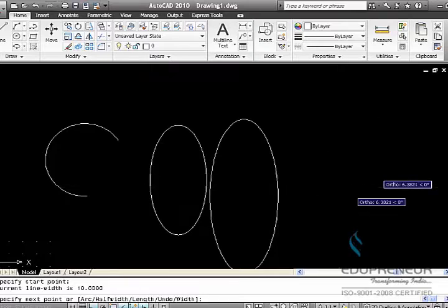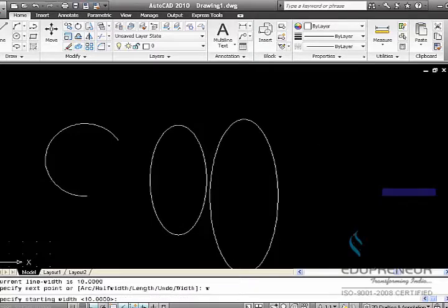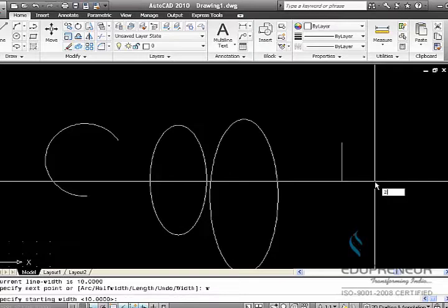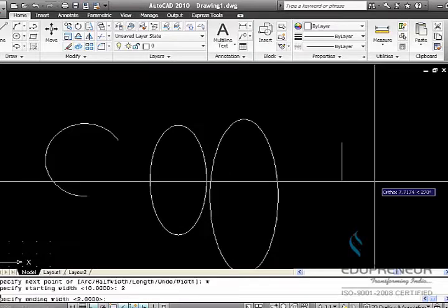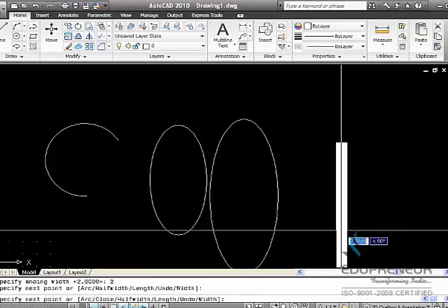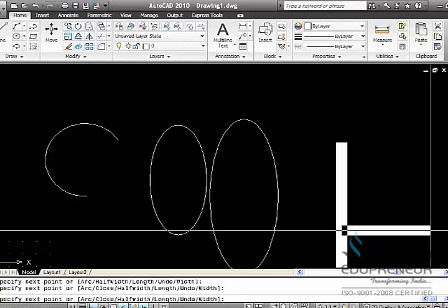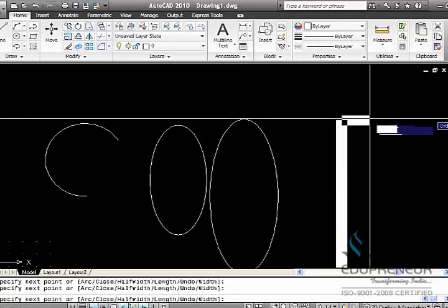Here we have previously specified the width. So let us press W in the command window, press enter and specify another width which will be just 2, so that the line won't be this thick. The end width will be again 2, so that the line will continue with the start and end point in the same thickness. It will continue drawing. This is specifically used by civil drawing draftsmen for their walls and other specifications in drawing. And when we press enter, the drawing will be ended.